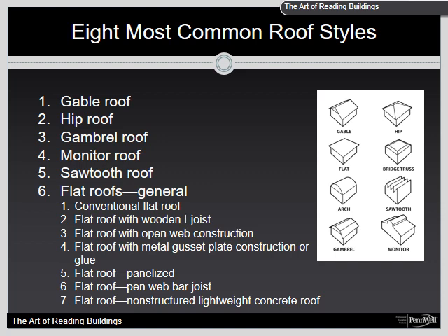If this roof is constructed today with modern material, expect lightweight construction that is covered with a 1/2 inch plywood or OSB. Sawtooth roofs are normally of older design and construction. Early collapse of main structural members of conventional construction for sawtooth roofs should not be a primary concern. Typically, the complete underside area of a sawtooth roof is exposed to the building content.